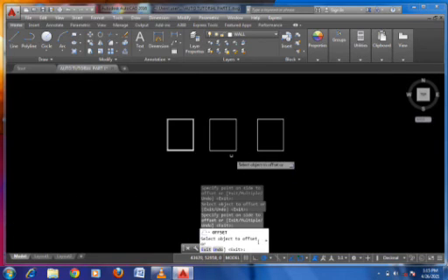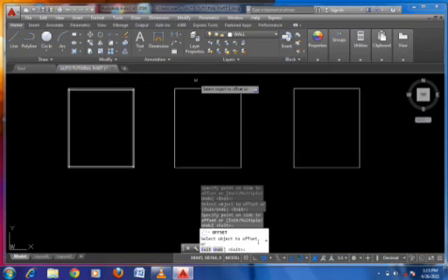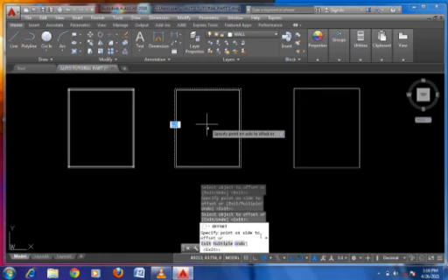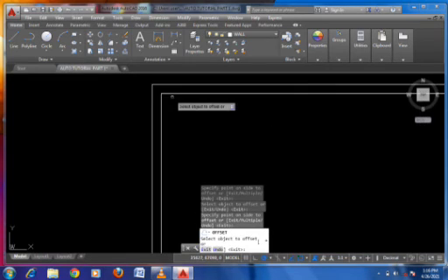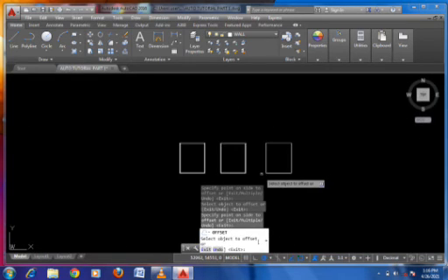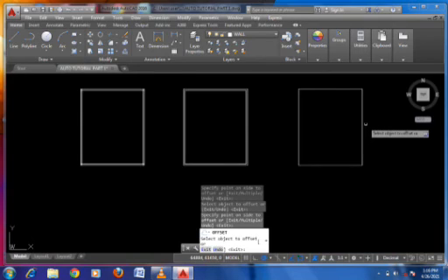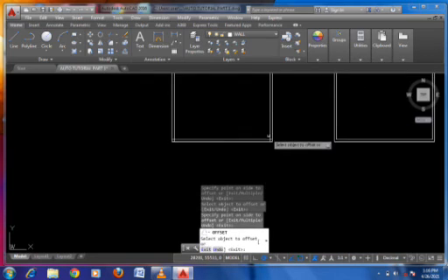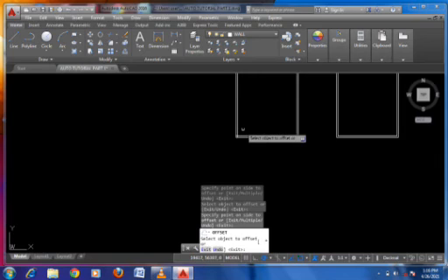So now if I want to offset my polyline, because the lines are in one entity, I can offset them at once. I'll just click on one part, and I'll just take it inwardly. You can see that it offset at once because the lines are continuous, they are together. Same thing for my rectangle line here. If I just click on one part, I take it inwardly. So that is how my external work is done.